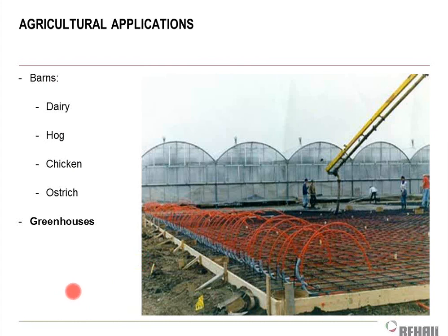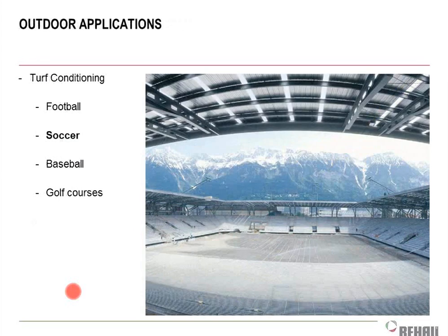And then greenhouses for planting. If you want plants to grow year-round in a glass cold box, you better find a way to heat them. And if you put in ceiling-based unit heaters and things like that, they are going to eventually get wet from all the moisture you're putting into that building and not do as well. Radiant floor doesn't have that problem, obviously.